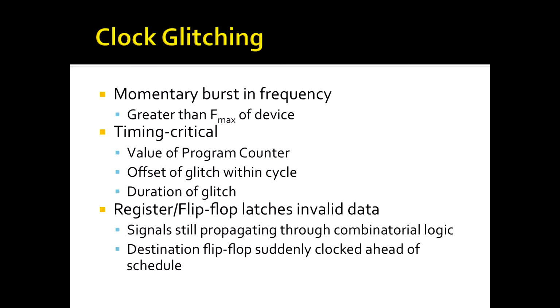So basically what this does is it causes registers or flip-flops inside the device to latch invalid data, because signals are still propagating through combinatorial logic through the device when you suddenly clock it.